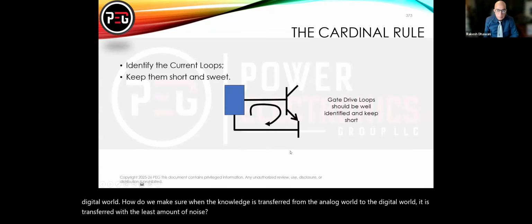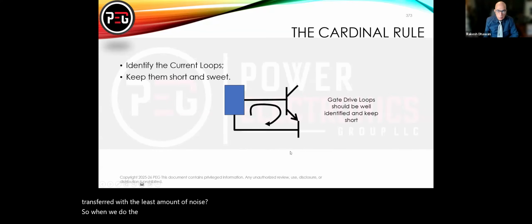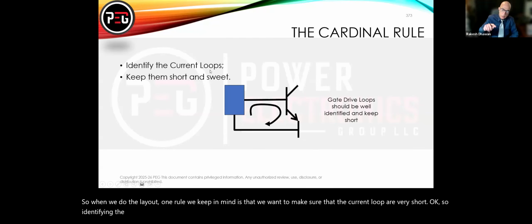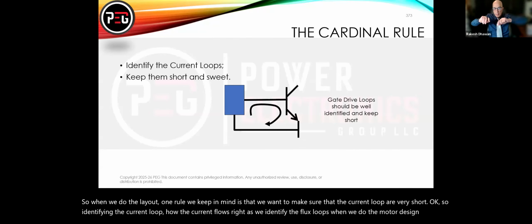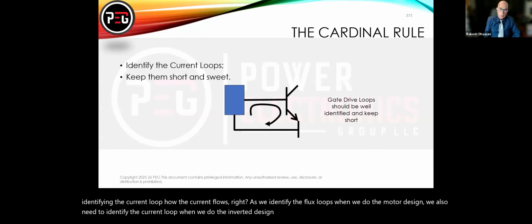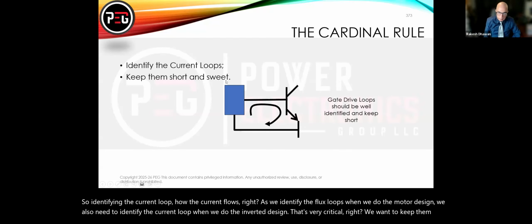When we do the layout, one rule we keep in mind is that we want to make sure the current loops are very short. So identify the current loops, how the current flows, right? As we identify the flux loops when we do the motor design, we also need to identify the current loops when we do the inverter design. That's very critical, right? We want to keep them short and sweet.